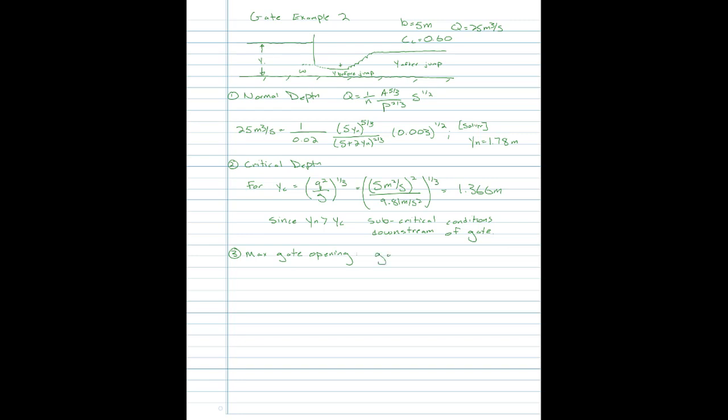So the gate is opened such that after contraction the water depth is equal to the sequent of the normal depth.